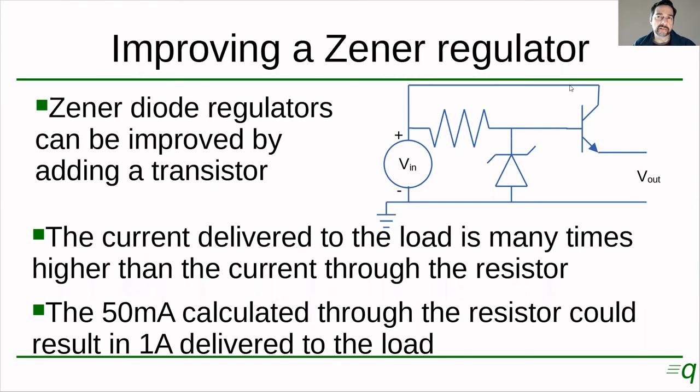transistors have a parameter called beta that is the current gain of the transistor. So basically what it does is when you have a load here that varies the current, the transistor is going to be supplying the current through this path. This is called the collector and this is the emitter, right? So the resistor will be supplying the current through this path, and the current supplied through the base, this terminal is called the base of the transistor, is going to be much, much lower.